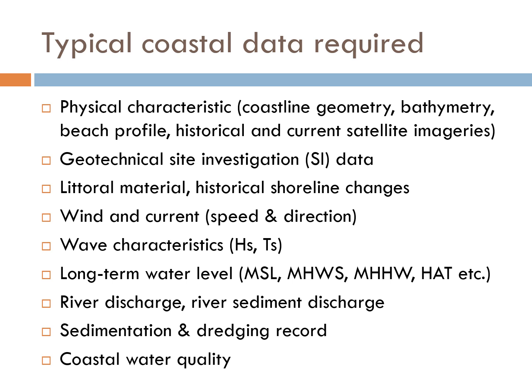In order to carry out coastal design, the typical data required are as listed in this slide here. We need information regarding the physical characteristics of the site, which includes coastal geometry, bathymetry, beach profile, as well as historical and current satellite imageries, so that we are able to look at the changes that have taken place in the past, specifically related to the shoreline changes or sandbar changes.